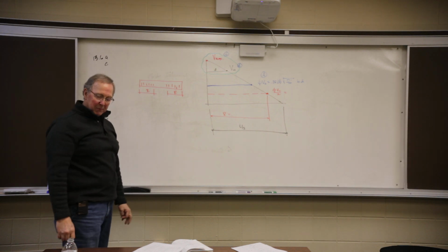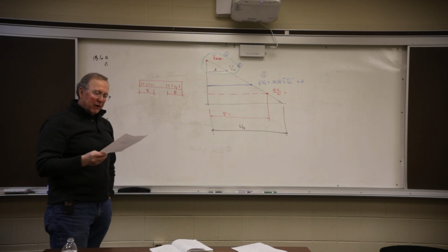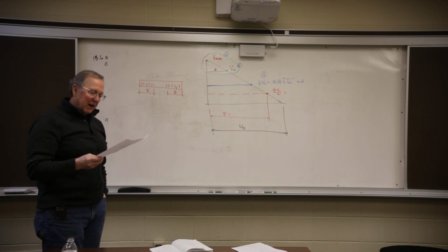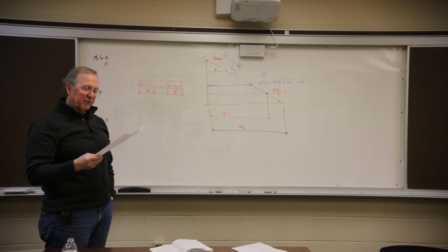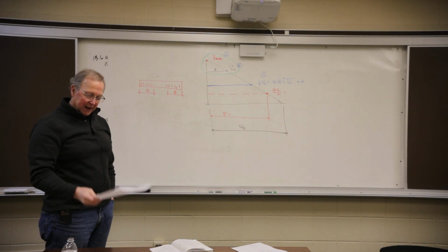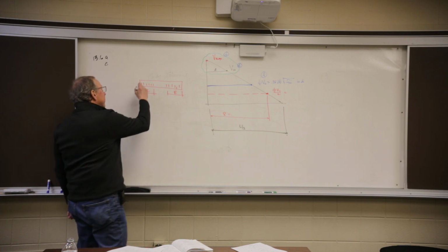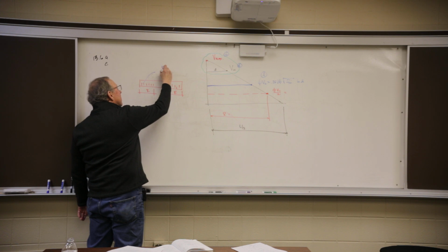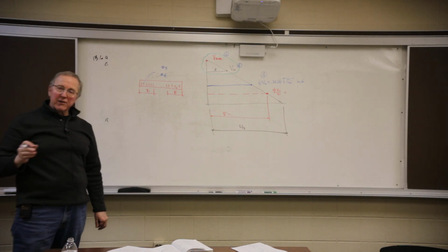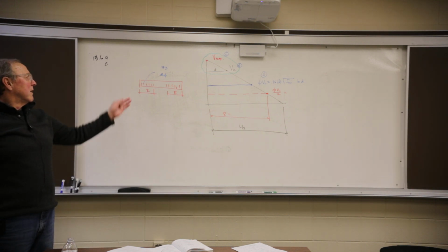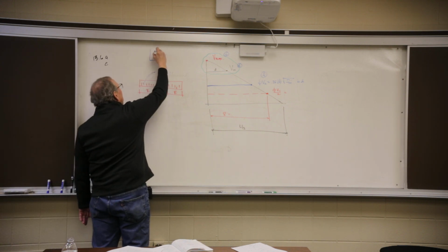Okay, so we got to know where they're going. Then we got to know if the bars are big enough. Big enough is letter L. The area of shear required is based on the formula in letter L. If our bar is big enough, we're fine. If it's not, we go up to the next size. So stirrups typically don't wander much in size. Stirrups are typically a number 3 bar or a number 4 bar. A 3 bar is 3/8 inch diameter, a 4 bar is 1/2 inch diameter. Why? We can bend them. If you notice me, when I drew them before, I drew a U or an O.